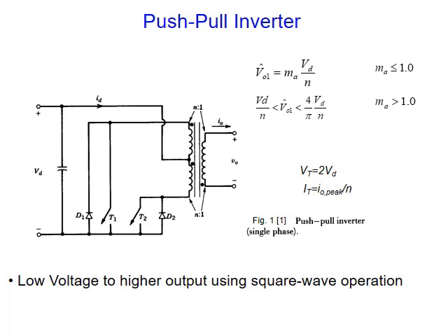we use only 2 switches, but we use at the same time a transformer, center tap at the primary side. You mean the primary side here you have a center tap, in this way. How does the circuit work? Have a look. Definitely these diodes are the freewheeling diodes connected in anti-parallel with the thyristor, as you explained before. And let's assume T1 will conduct,